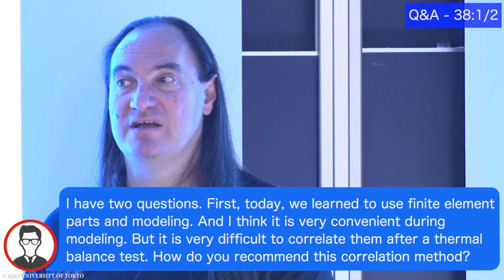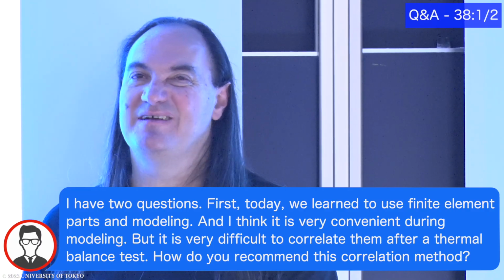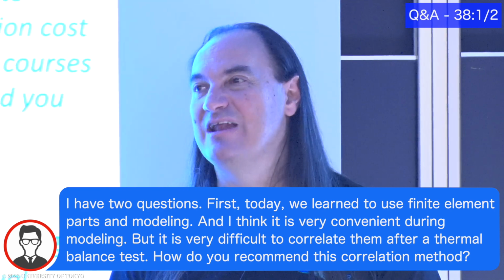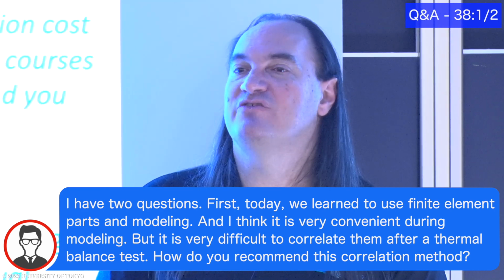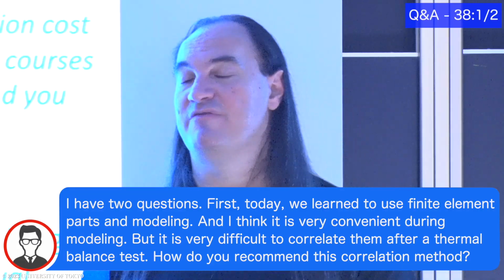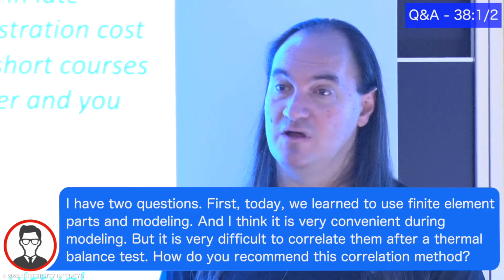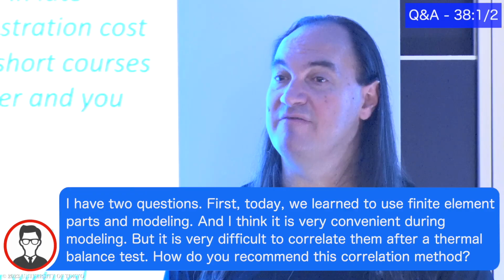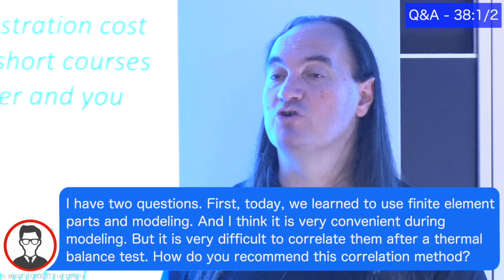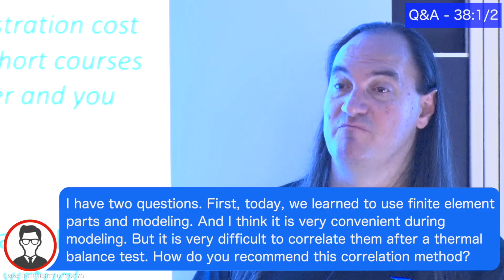We're not changing the mesh. You might add some fidelity if it wasn't there before, but I don't think that the geometry is the primary area that we target when we're correlating. I think it's much more interface conductance uncertainty, E star values, possibly radiative behavior for things. So I think that the mesh approach that you have for pre-correlation and post-correlation would remain much the same.